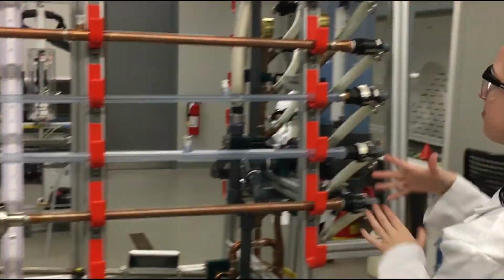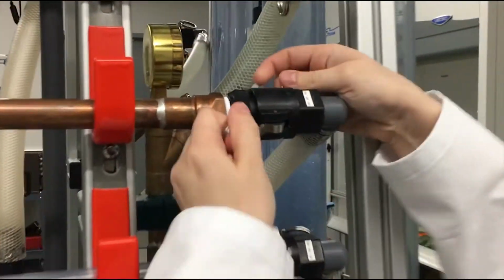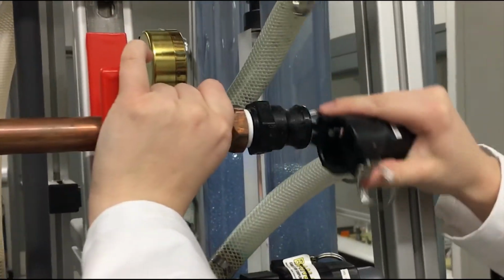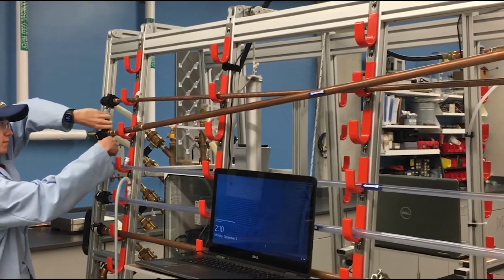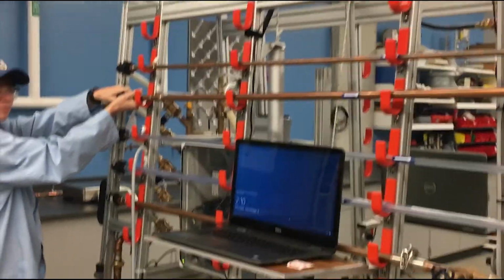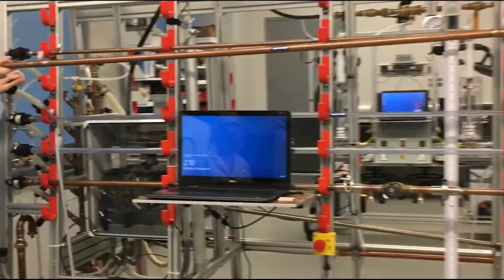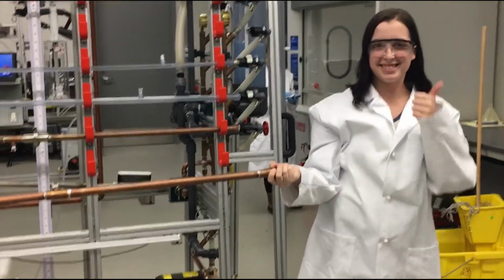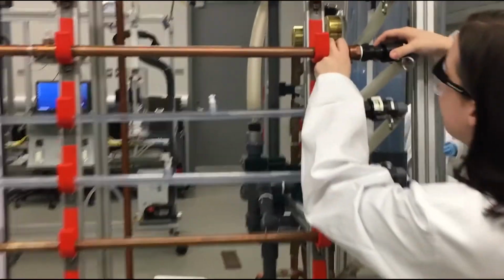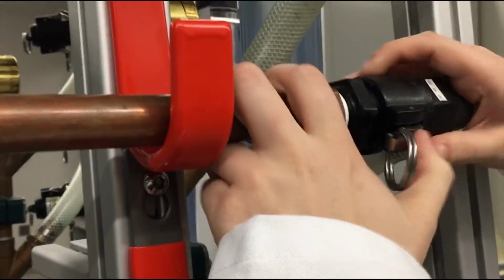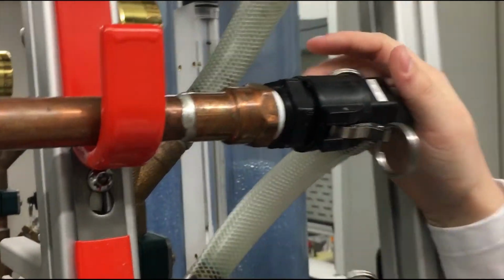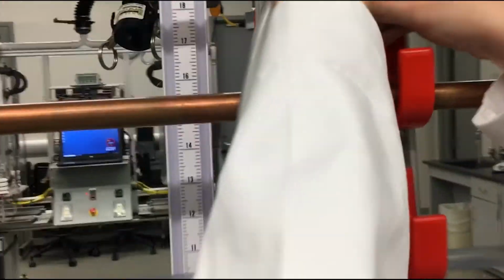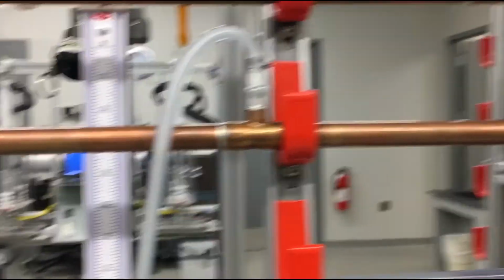One person should unlatch the pipe farthest from the valve and tip it to send any remaining water in the pipe back to the tank. With both ends unlatched, carefully take the pipe off the rack, being aware of other objects and people in the lab. Before starting the pump, ensure the pipes are tightly latched with the cam locks on both ends and check that at least one valve is open at the end of the pipe to prevent restricted flow. Attach the 2 pressure transducer lines to the pipe.